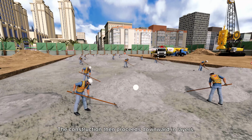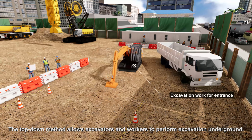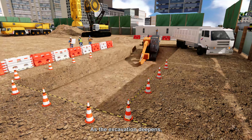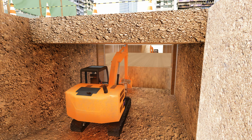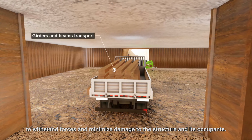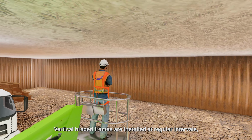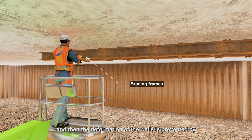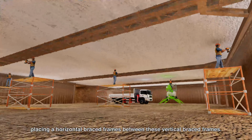The construction then proceeds downward in layers. The top-down method allows excavators and workers to perform excavation underground. As the excavation deepens, the tunnel structure is built incrementally. A bracing system is added to improve the cover slab's ability to withstand forces and minimize damage to the structure and its occupants. Vertical braced frames are installed at regular intervals, and then the deformation of the walls is prevented by placing horizontal braced frames between these vertical braced frames.